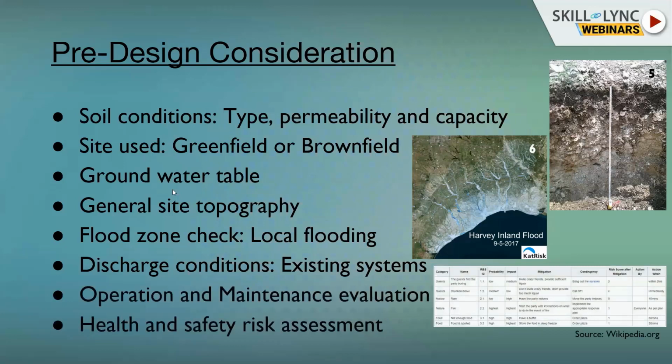And the last is the operation and maintenance evaluation. It's really important in SuDS that we decide who is going to operate and what will be the maintenance frequency of these elements or components. And the last but not the least, health and safety risk assessment. For example, one of the SuDS components is an open pond or a detention basin.